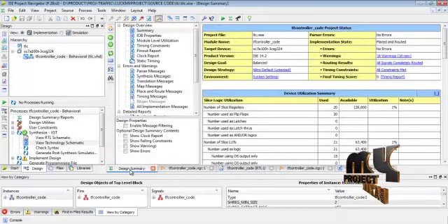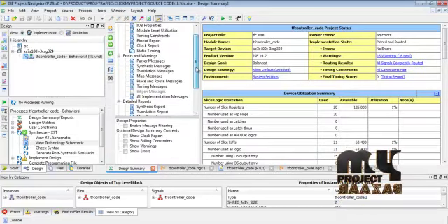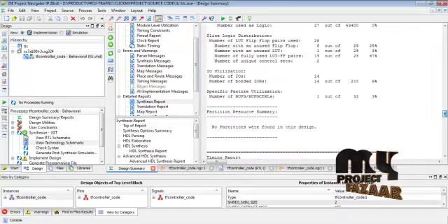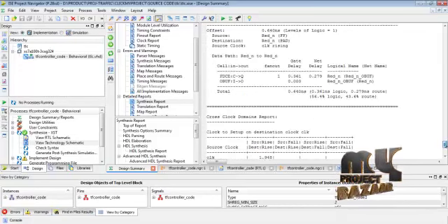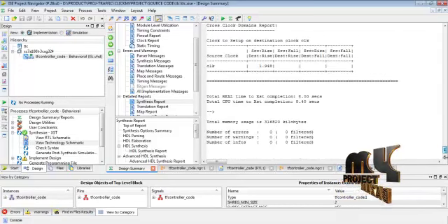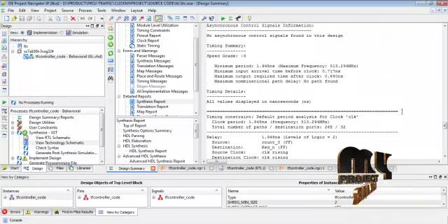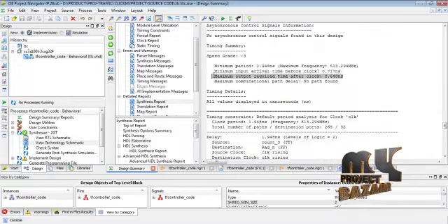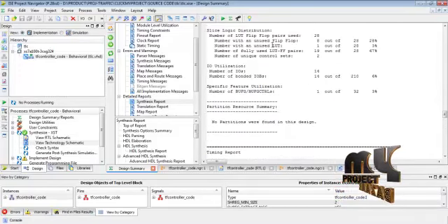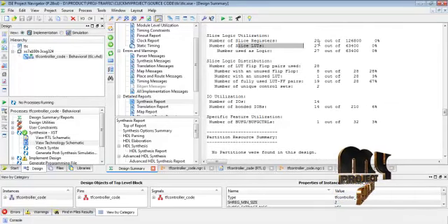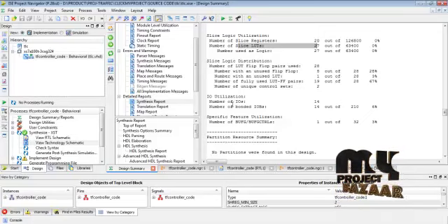Then we go to the design summary process. This design summary is mainly used to select the synthesis report for the overall architecture result. This report covers the device utilization function, the processing time and the delay time for the overall architecture results. This is the processing time and the processing frequency for speed. Then we calculate the latency level for the traffic light controller architecture. This is our device utilization for the overall architecture. Then we count the slices and lookup tables, then flip-flop pairs, then the bonded input-output function for the overall architecture.